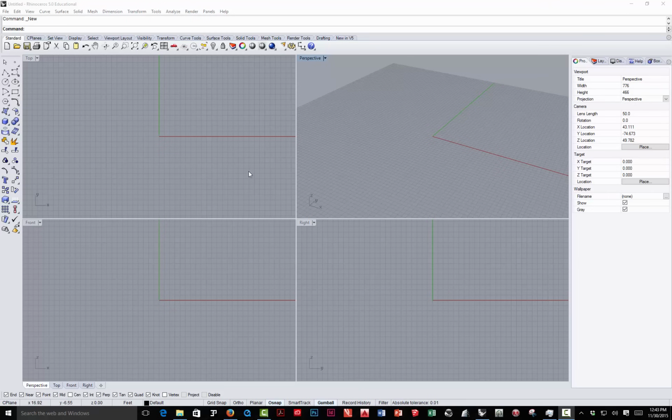The first thing I want to mention is I'm going back and using the same AutoCAD files that we used for the SketchUp model. We already went through that W block process. Basically that takes a more complicated AutoCAD file, which is what you're always going to be working with, and you pull out the pieces that you need. Now, Rhino actually is really good at handling AutoCAD files with full layers and everything, so you could just bring the whole Healing Garden AutoCAD file in here and use it, but you have to go through and manipulate more layers. But having some of those layers is actually helpful to be able to turn things off and on.